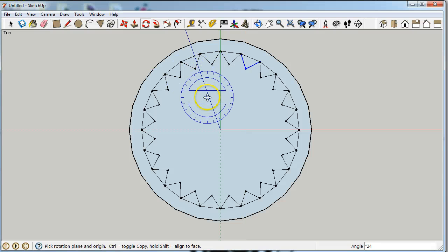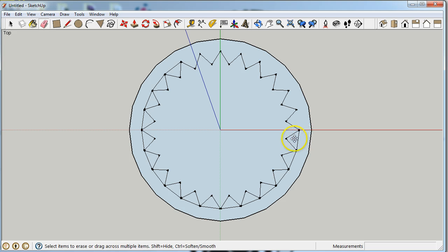So all you need to do from here is take the eraser tool at the top of the toolbar and erase unwanted lines so that we are then able to start the bubble wand itself, remove the inside face, that blue area in the inside, and give it a thickness so that the bubble wand will then be complete. So as you can see, I'm going through and I'm erasing each of these individual lines so that they are no longer there and that we can move on.